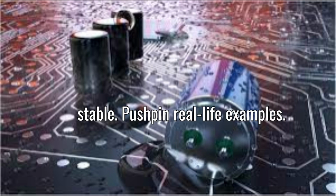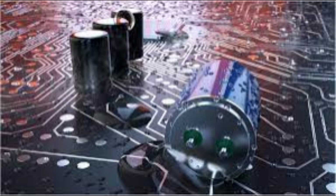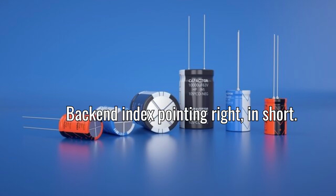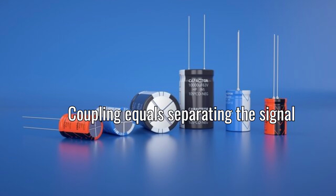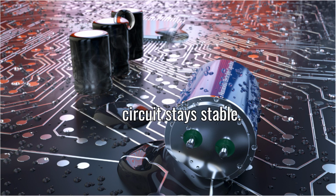Real-life examples. Coupling: audio devices, radios, and TVs, passing only the signal you want. Decoupling: computers, phones, and any digital system, keeping the power clean. In short, coupling equals separating the signal from unwanted baggage. Decoupling equals calming down noisy power, so circuits stay stable.